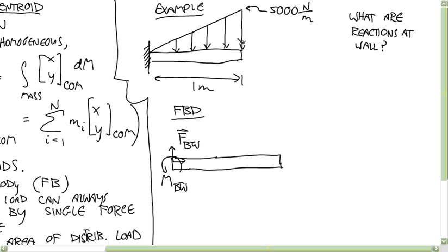And then this distributed load has a triangular shape. Where's the centroid of a right triangle? Do you remember that? I did an example last time where that came up. 1/3 from. Yep, 1/3 from, so it's up 1/3 and it's 1/3 from both of the fat sides, right?